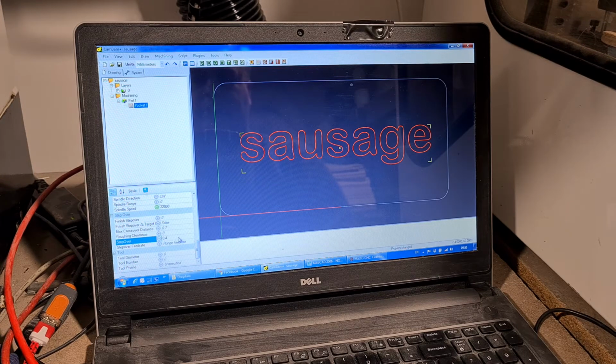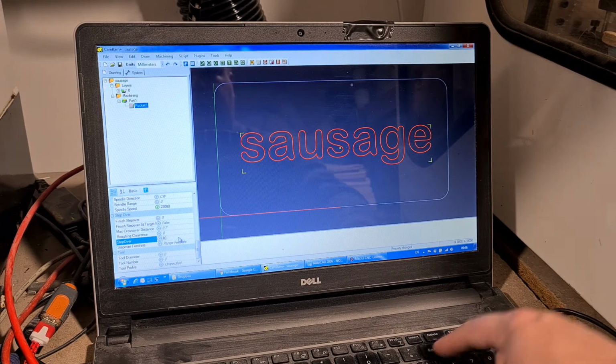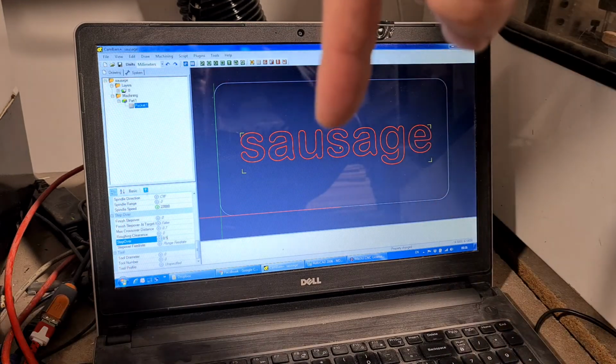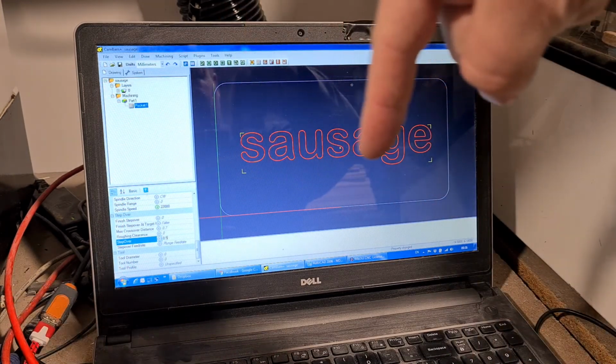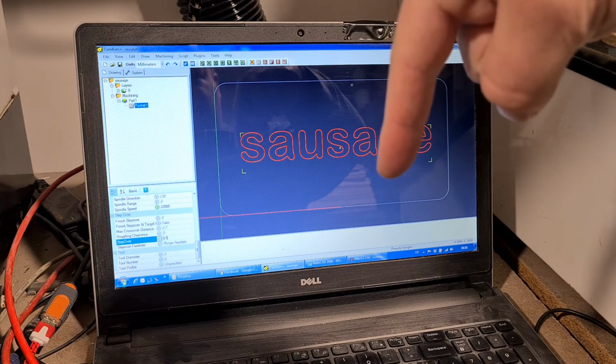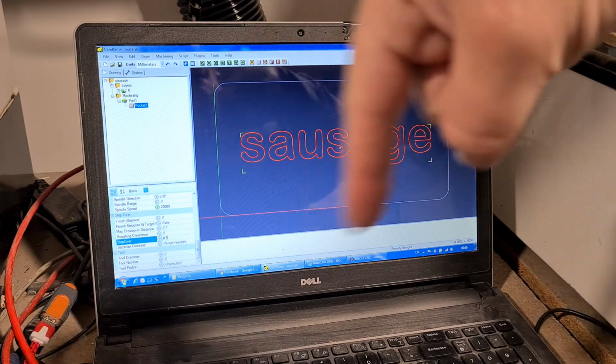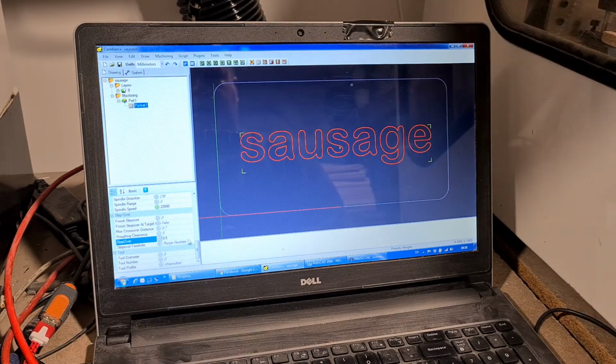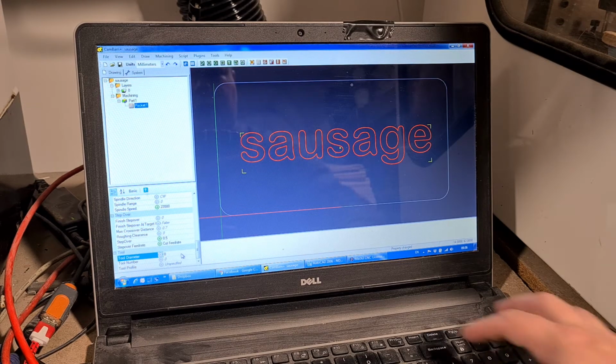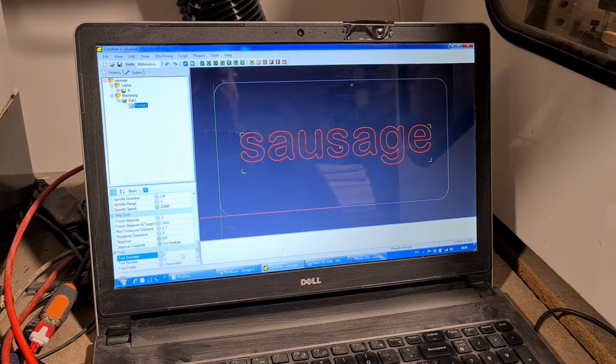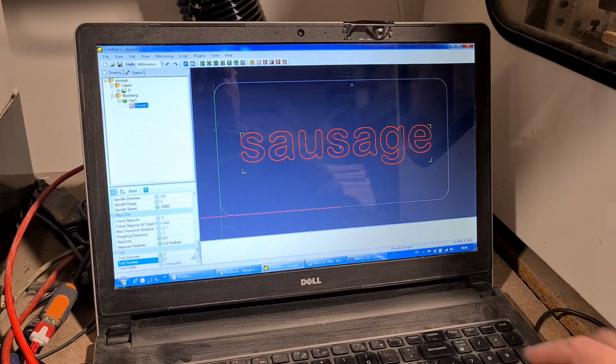And what we're going to do is change the step over from 0.4 to 0.5. So that's, once it's done a pass, it's coming to do the next one, how much it moves over and engages the tool. So I like to do the tool at 50% engagement. It reduces the amount of passes and just speeds up the cutting process a little bit. Tool diameter, we'll see how 2 millimeter comes out. Tool number again, we'll put it as 1 for this purpose.